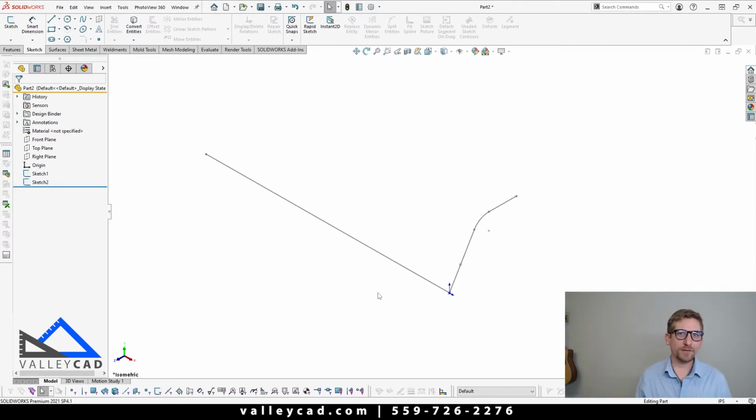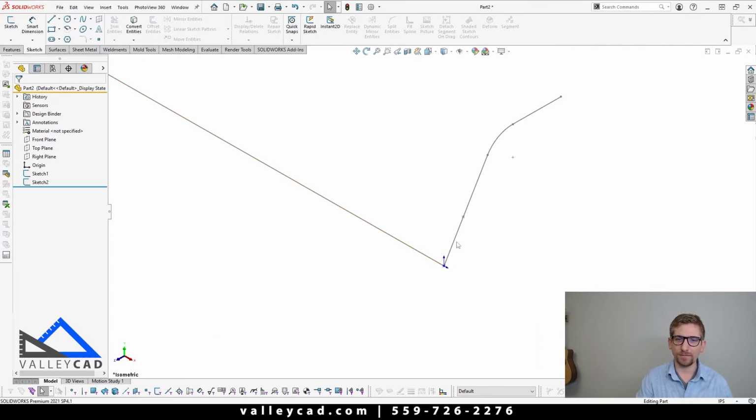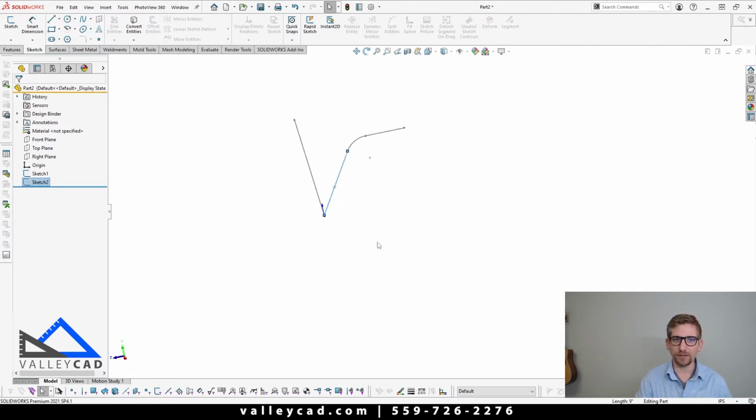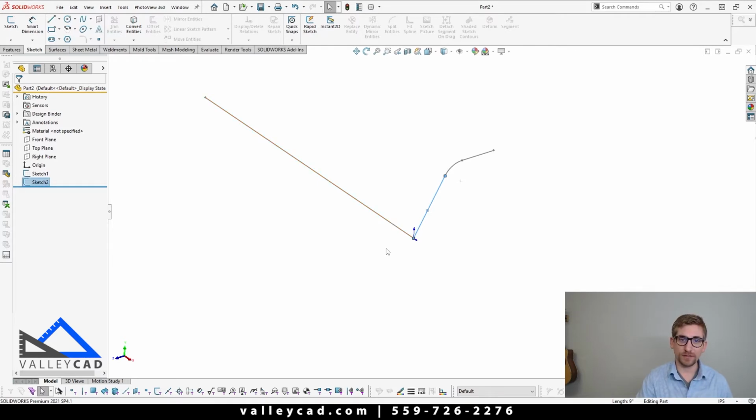So you might have a scenario where you needed to make two separate sketches, and with these two separate sketches you need to now show this as a fillet transitioning from this angled line coming down to this horizontal line. Now when you're working with filleting, you're not able to do that between two separate sketches. And you can see that in my design tree here actually. So what we need to do next is this thing called a composite curve. And what that does is it merges more than two separate sketches into one.